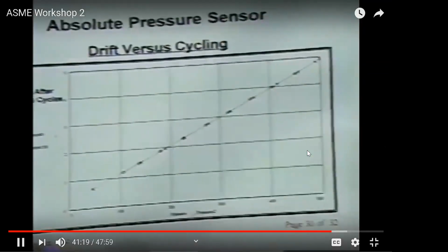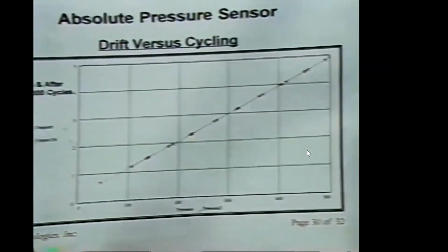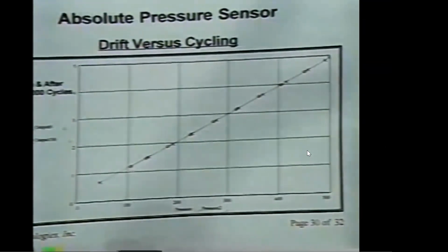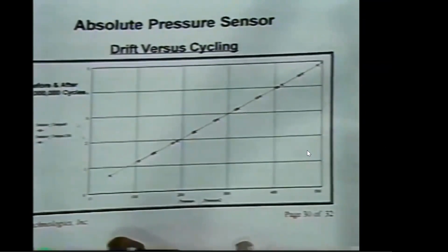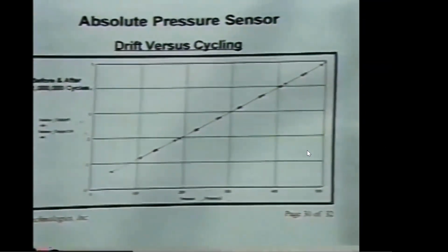Historically, one of the big negatives that has been said in the literature, as well as by people, about polysilicon membranes is that the material is very difficult to reproduce reliably, and that the material may fatigue or may show a significant amount of hysteresis over time.